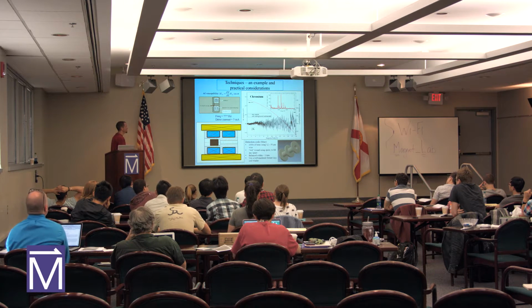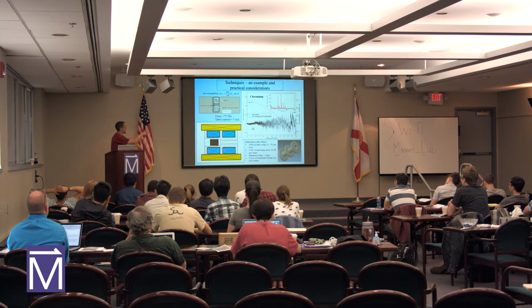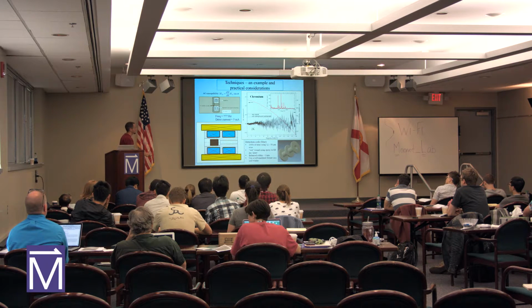So that's a balanced coil set. And when you have a balanced coil set of detection coils inside the excitation coil, and you put a sample in just one end of the detection coils, like shown here and here, you can detect the magnetization of the sample. So it's not that easy to put these together, but they're incredibly sensitive.